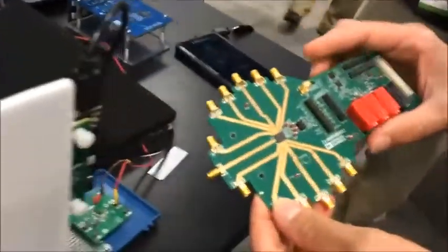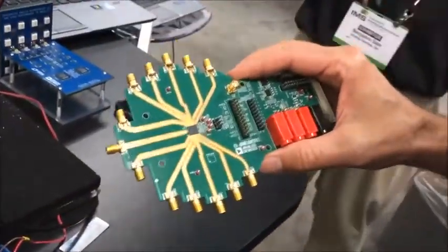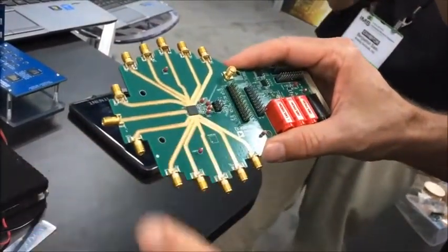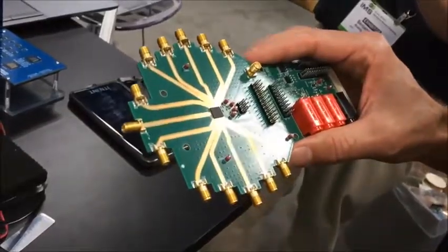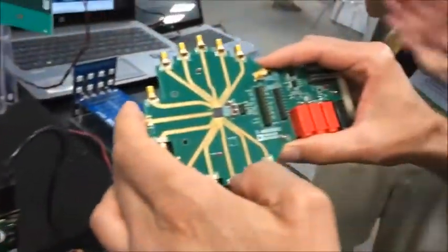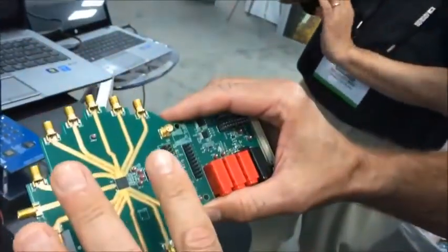All right, so I'm Pete DeLoss with Analog Devices in Greensboro, North Carolina. So we're demonstrating some of our analog beamforming ICs that are being released. They're 4-channel transmit and receive, X-band, 8.5 gig up to about 15 gigahertz. And our demo here, this is our eval board, common input, transmit and receive outputs here.